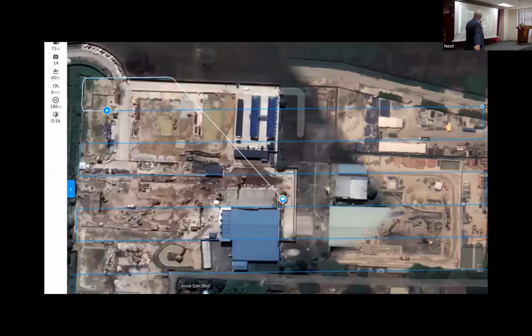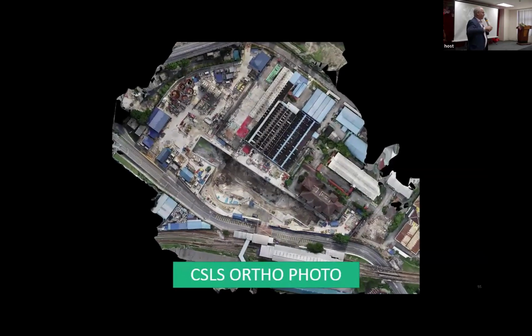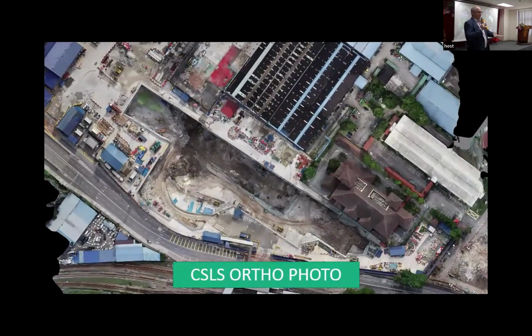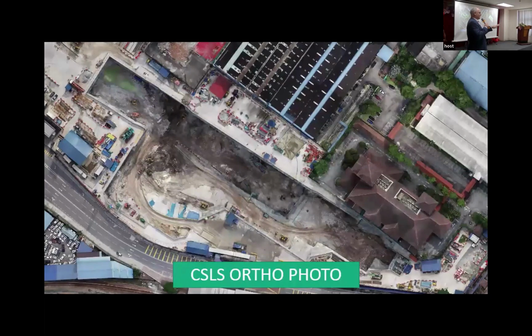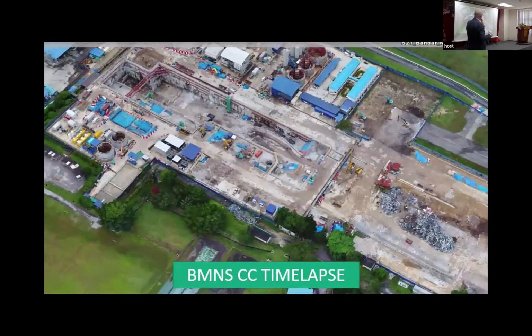So you can set up the track for the drone and it will fly the same path every time. And then once you've collected all the photographs, the first thing you can produce is a proper two-dimensional, we call them orthomosaic picture of the site. This is dimensionally accurate. So I can use it as a background for my models, I can use it in my GIS system, and I can use it to monitor things.